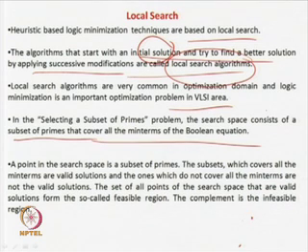Okay, so when I say that you remove some of the prime implicants and add some others, you are going from one solution to another solution, and both of them should cover your function. That is what is called the search space. The search space is a subset of primes. A subset of primes covering your function is a solution. Now you exclude some primes, include some primes, and this is another solution which is nearby.